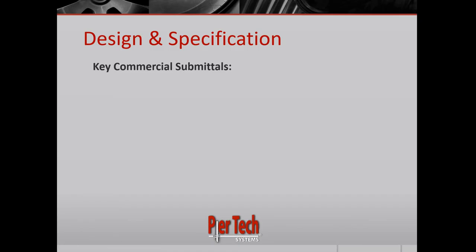All right, so I want to get into design and specification for commercial projects and what kind of things you're going to be seeing for submittals, and what you're going to be seeing required for the drawings, working drawings for the project. So the first part of the submittal is you're going to see that piles will need to be installed by an authorized installation contractor. So you want to make sure they're authorized by the manufacturer of the pile they're putting in.